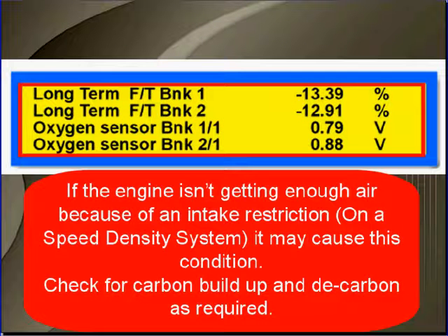When you have a rich condition, you either have not enough air or too much fuel. If the engine isn't getting enough air because of air intake restrictions, and this would be on a speed density system, it may cause this condition. Check for carbon buildup in the throttle bore. If you have carbon buildup in the throttle bore, your decarbonization process must address the throttle bore, the intake manifold, and the back of the intake valve.